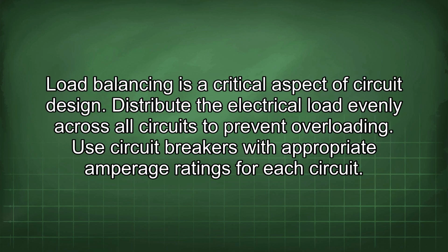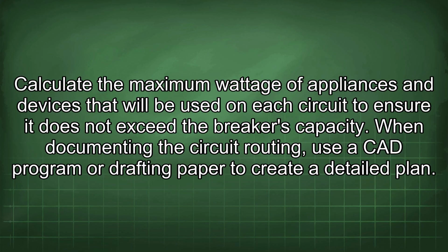Load balancing is a critical aspect of circuit design. Distribute the electrical load evenly across all circuits to prevent overloading. Use circuit breakers with appropriate amperage ratings for each circuit. Calculate the maximum wattage of appliances and devices that will be used on each circuit to ensure it does not